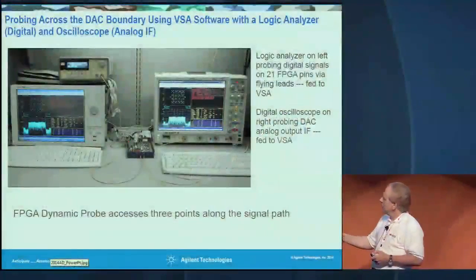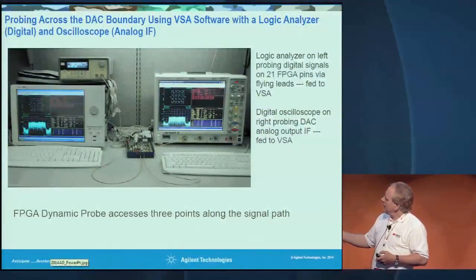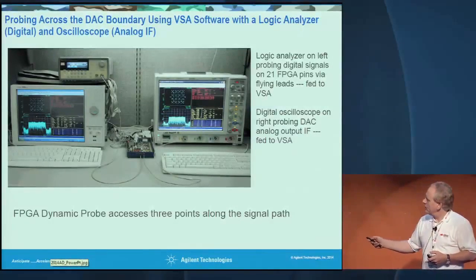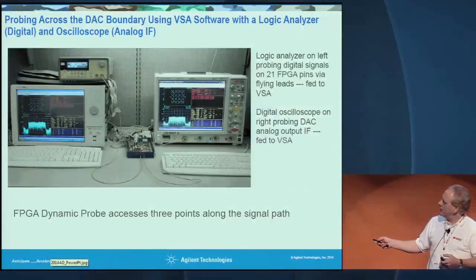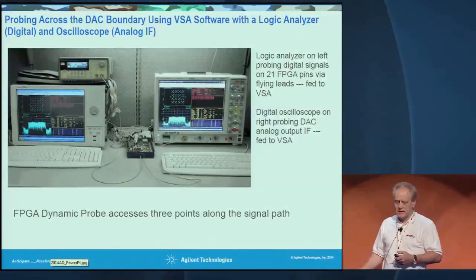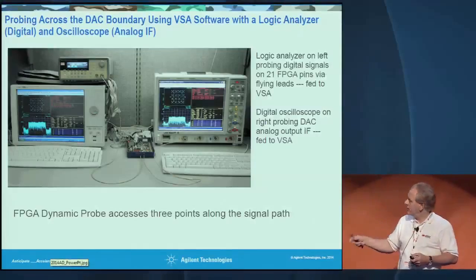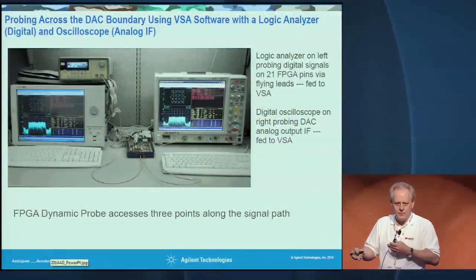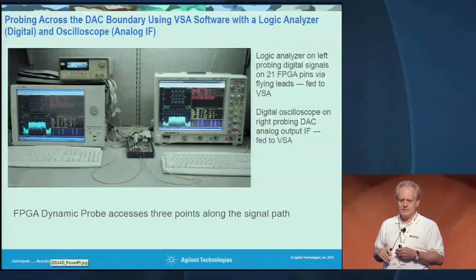So here's an example of using the VSA in a logic analyzer situation where we have a 21 pin ribbon cable looking at this Xilinx Virtex, looking at the pins, and it takes the individual pins off the bus and reconstructs what the sampled waveform value would be, because realize you probably have a serial stream of data, and it reconstructs the communication information from the raw data stream.